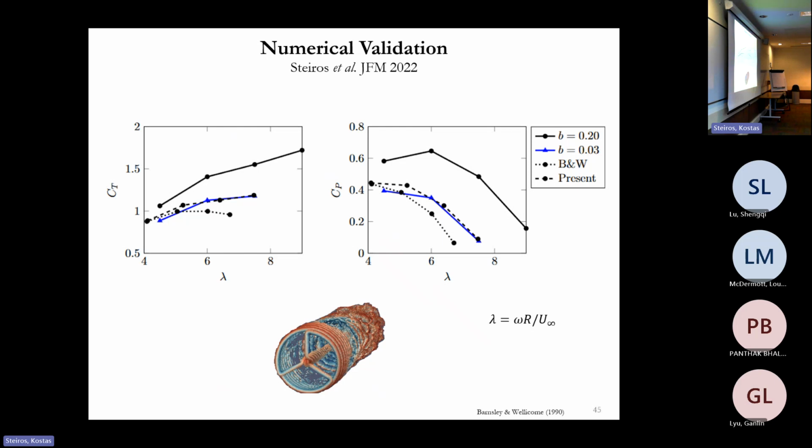However, our model, the dashed lines, is more accurate, especially at high tip speed ratios. At low tip speed ratios, the two correction models coincide. But as we go to higher and higher tip speed ratios, our turbine becomes more and more solid, right? And then we can see really how the new analytical model better predicts the real power consumption of the turbine.